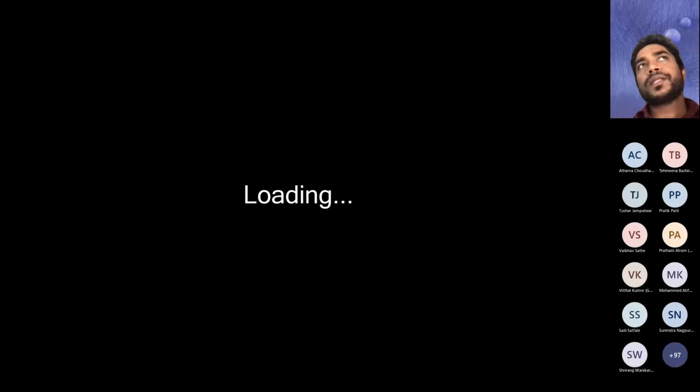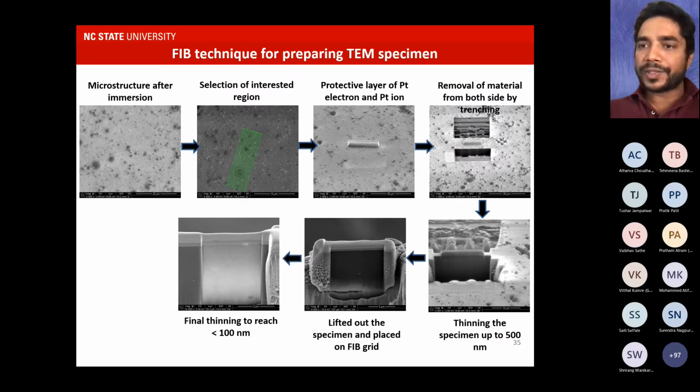We did lots of surface film characterization by XPS and SIMS. I'm not presenting all these details, but what we learned is that these materials are really heterogeneous. So we thought, can we characterize the surface film wherever we want? We wanted a technique with really high depth resolution and high lateral resolution. XPS and SIMS give really high depth resolution, but they lack lateral resolution, and we cannot focus on the point we want. We want a few nanometers of lateral resolution. So we thought of using TEM, which is not conventionally used for studying these surface films.